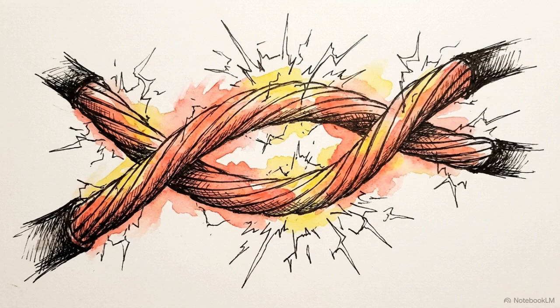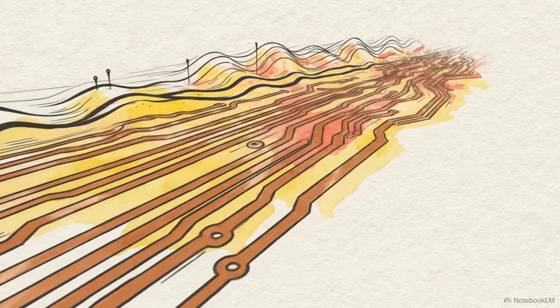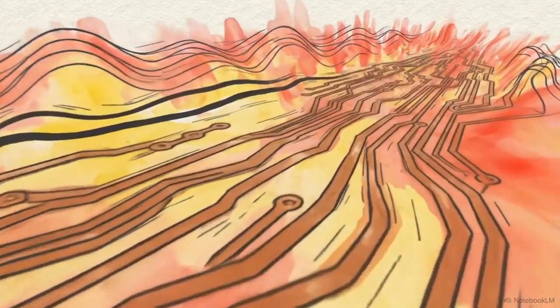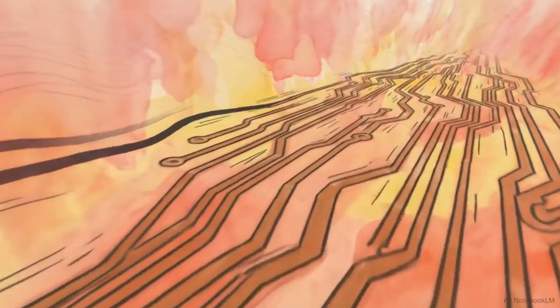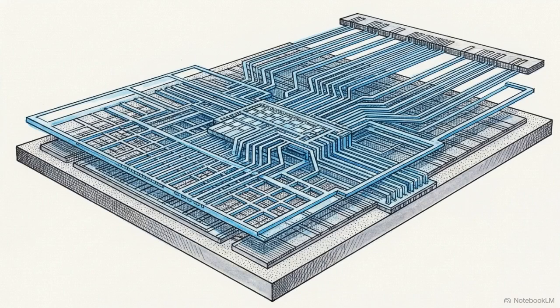The alternative to building denser physical connections is trying to push more data over fewer wires by scaling up the analog frequency to 100 GHz or higher. Pushing extreme frequencies over copper requires aggressive voltage. It generates excessive heat, creating a power ceiling that makes high-density chiplets impossible to cool. By utilizing the tight geometry of microbumps, hardware architects can instead deploy wider data paths running at slower digital frequencies, completely avoiding the power tax of extreme analog scaling.